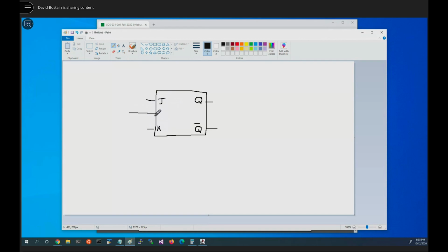If the clock just comes in and butts into the chip itself, that's a level clock. As a matter of fact, it's level on the high signal, so it's a positive clock, a high signal clock. It would be active when this is active, if this is the clock here. And usually it'll be labeled on the chip as clock. If it's on the low edge, or low level, like here, there'll be an extra bubble right there.